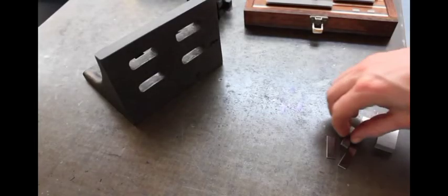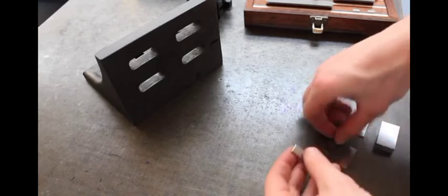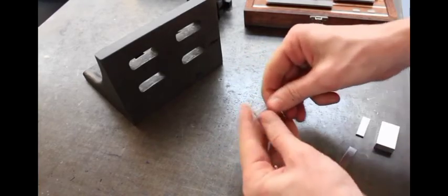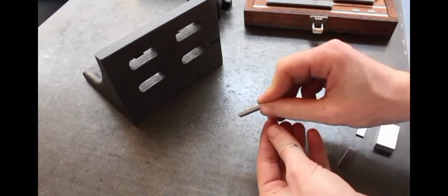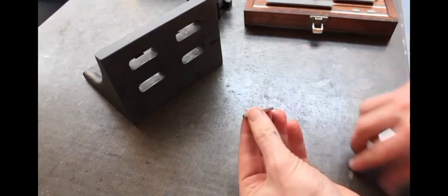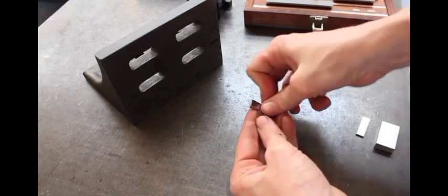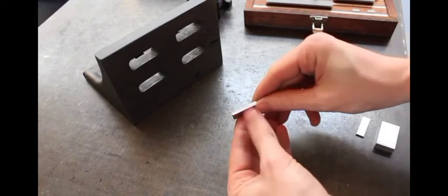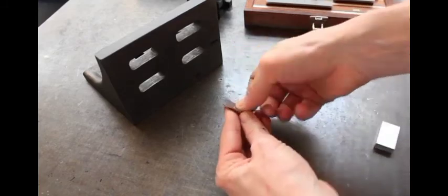Once we've chosen our slips, we need to ring them together, which means basically put them at 90 degrees and twist them with a little bit of pressure, and they'll stick together due to molecular attraction. Now, what I'm doing here is actually bad form. You shouldn't put them in contact with the surface plate and certainly not slide them like I did, but we're showing the point that they will stick together to create the accurate height.